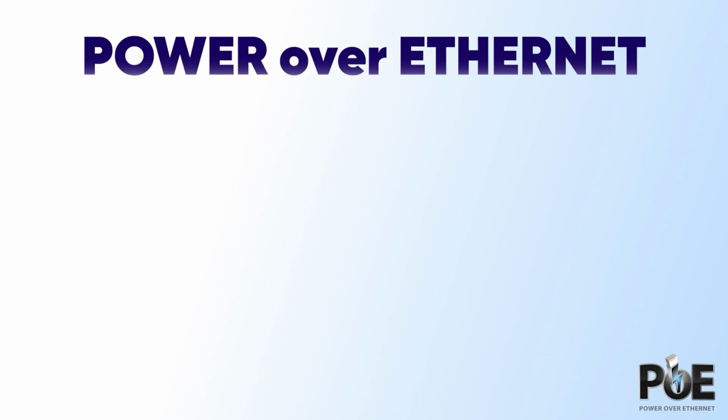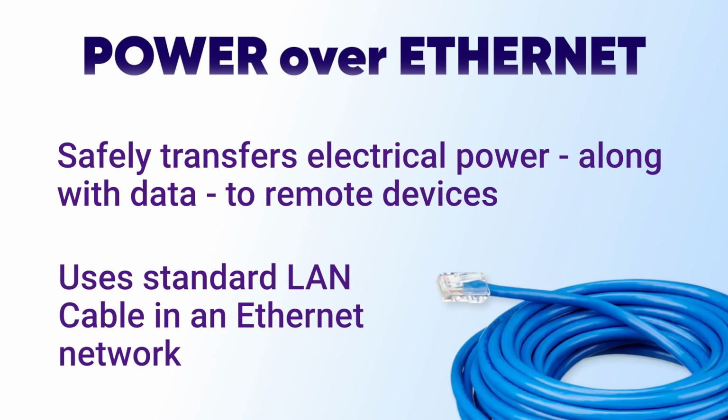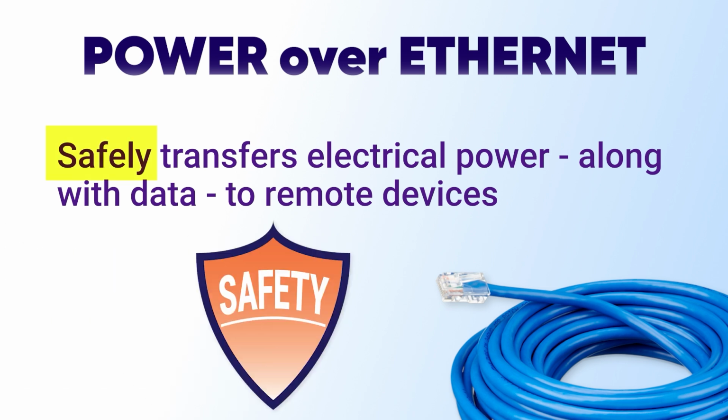Power over Ethernet is a system that safely transfers both electrical power and data signals to a remote device. It does this using a standard LAN cable, also known as a network cable. Low-power versions of PoE can operate over Cat5 cable, but higher power versions require better cable like Cat6 or Cat7. The IEEE standards for PoE emphasize safety. There are means in place to ensure that electrical power is sent in a safe and reliable fashion.